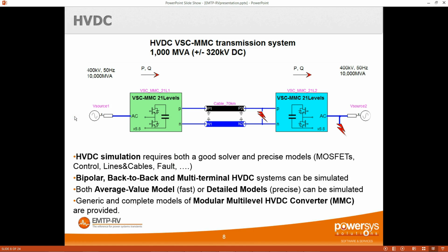Obviously, here all the nodes are not connected to each other, and if you have to draw the admittance matrix of a network like that, it will be most of the time 0. And it's like that in most networks. So a sparse matrix allows the engine not to consider those 0s and only to perform the important calculations, and it helps to save a lot of time on those huge systems. It actually increases the speed of the computation by an exponent of 3, so it's very important.